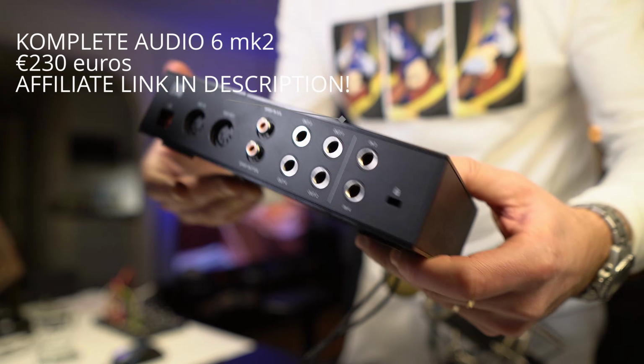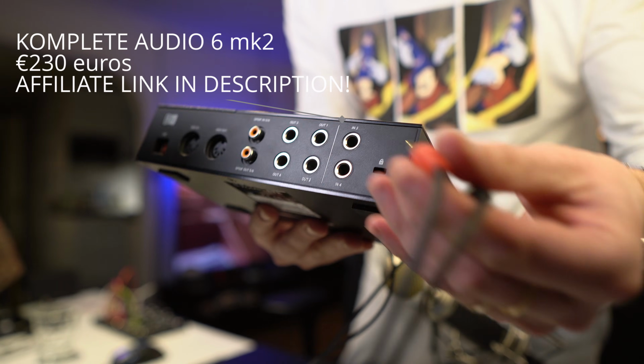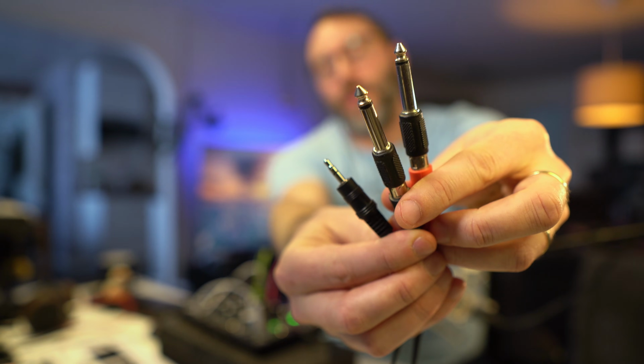You will find DC coupled outputs on more expensive audio interfaces like Mo2, etc. But luckily we have the Complete Audio 6, which is only around 230 euros, which also has DC coupled outputs. Bear in mind that the Complete Audio 6 is USB powered, so it's limited to plus minus 2 volts of DC output range.